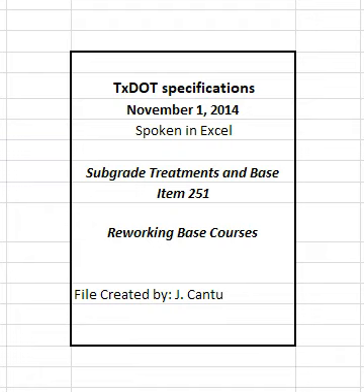4.3.2 Density control. Determine the moisture content in the mixture at the beginning of and during compaction in accordance with TEX 103E. Compact to at least 98% of the maximum density determined by TEX 113E, unless otherwise shown on the plans. The engineer will determine roadway density of completed sections in accordance with TEX 115E. The engineer may accept the section if no more than one of the 5 most recent density tests is below the specified density and the failing test is no more than 3 PCF below the specified density.